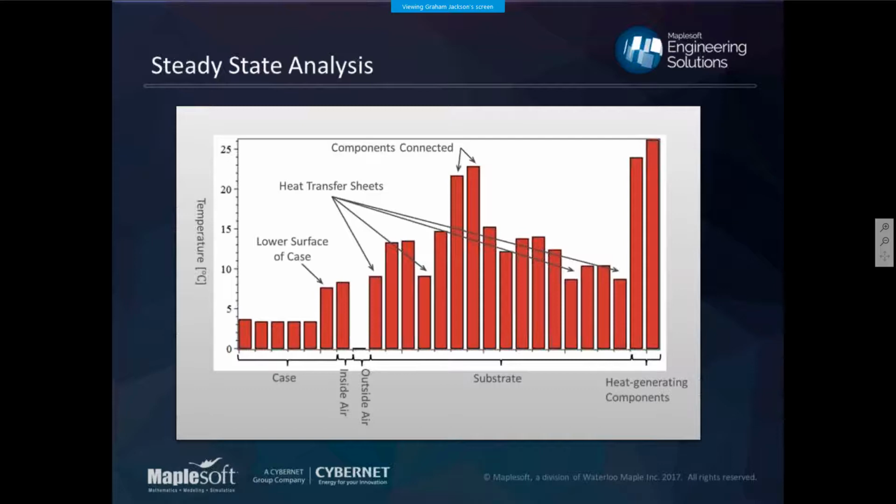And maybe we think about some countermeasures, where we want to replace some part of the case material. It's often plastic, these kinds of cases, but let's say you wanted to change that to metal or some other material with a higher rate of heat transfer. This can be expected to really help that out, and we can incorporate that idea into a model like this with the parameters we have set up.